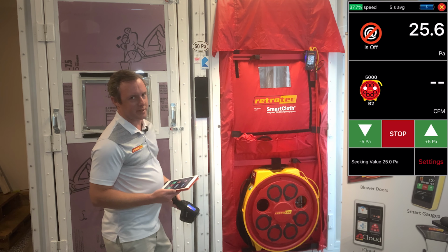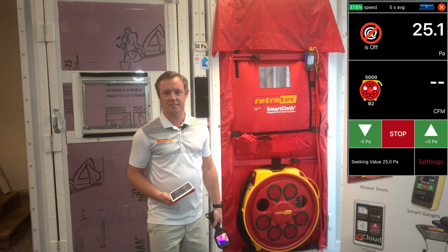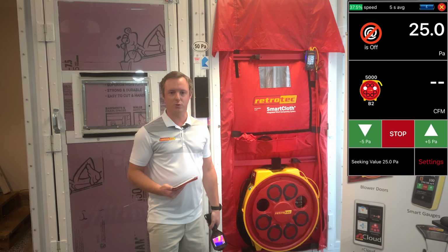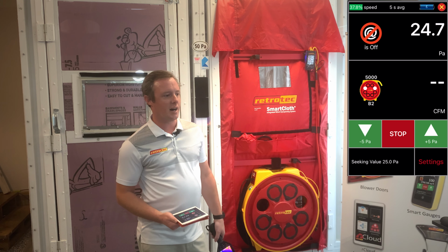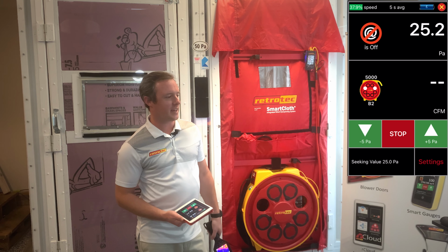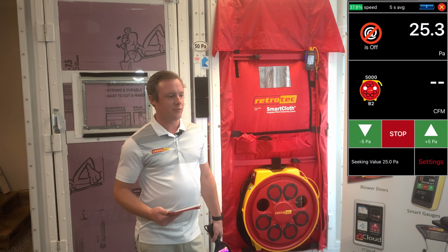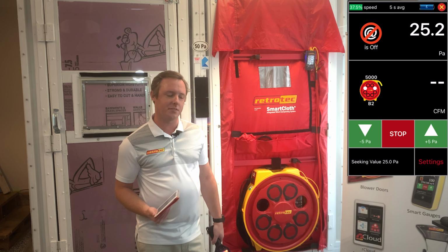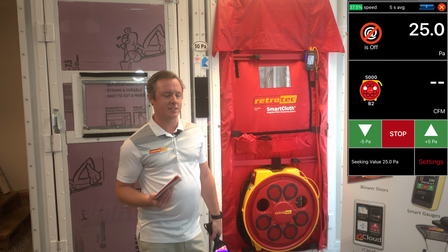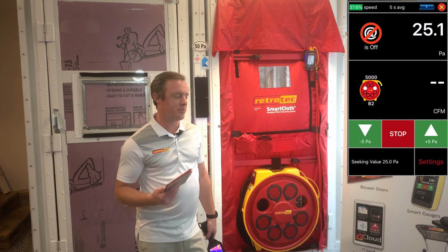A lot of times what we would be looking at are the types of leaks that we constantly see in ceilings, through floors, things like that. Ceilings usually are going to be more leaky than other parts of the house, just with all the different kinds of penetrations we have going through there for mechanical, electrical, and plumbing. Also where we have those cracks where the ceiling drywall meets the top plates. So a lot of times that'll show up pretty easily too.